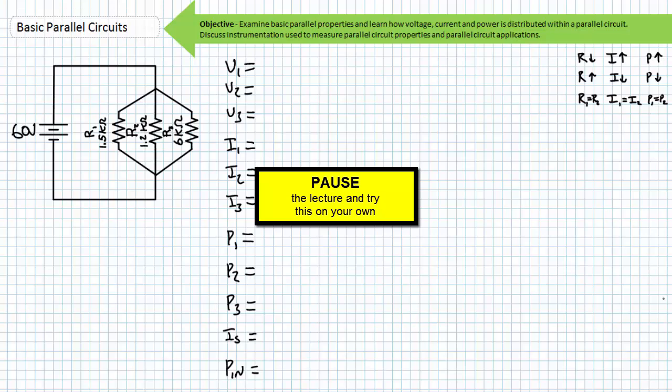Now, before you make a mess of this, let me impart this advice. Voltage across components hooked in parallel should be the same. The sum of currents entering a node should equal the sum of currents leaving a node. What goes in should equal what comes out. Current should be the largest through the smallest resistor in a parallel relationship. Current should be smallest through the largest resistor in a parallel relationship. Current should be the same through identical resistors in a parallel relationship.